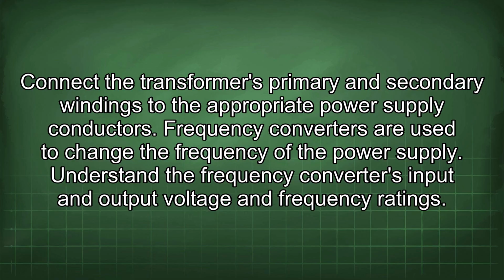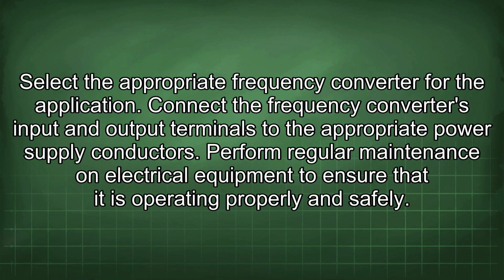Frequency converters are used to change the frequency of the power supply. Understand the frequency converter's input and output voltage and frequency ratings. Select the appropriate frequency converter for the application. Connect the frequency converter's input and output terminals to the appropriate power supply conductors.